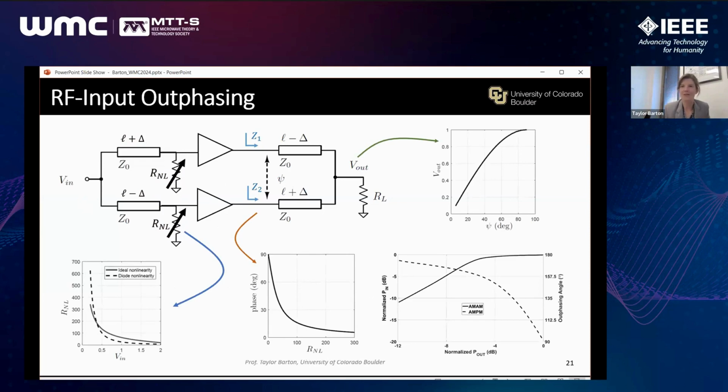I see a question about the digital splitting and outphasing versus Doherty. In terms of bandwidth expansion, I think they are comparable. The complexity is arguably slightly higher for outphasing because you're doing both phase and amplitude, but in practice in Doherty, you also need to account for AM-PM in your device. And so it's very, I would say, analogous in the sense that if you try to do dual drive Doherty, you're going to get a 5 to 7x bandwidth expansion that can really inhibit the instantaneous bandwidth that you're able to drive through your device.